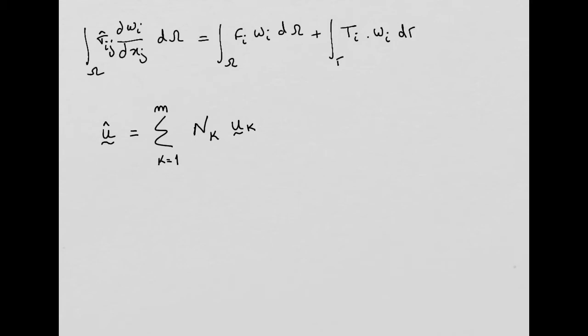You remember when we built approximation function phi previously in the previous sessions for the weighted residuals, I think we did that for a beam, so we built the approximated deflection as a summation of the shape functions, we call it phi, remember, times unknown coefficients.